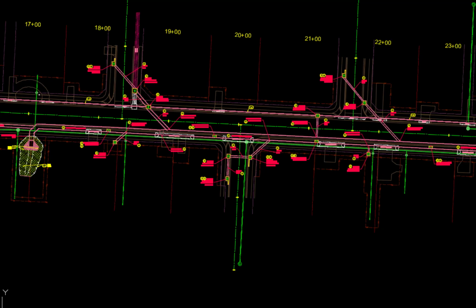In areas where the subsoils consist of clayey materials that do not drain well and become saturated during the rainy season, which is the case within the Kincaid road improvements, subsurface drainage should be installed along roadways in order to keep the subgrade dry. Where stormwater drainage facilities are installed, gravel is used for the bedding and backfill of the drainage pipe, which also serves as subsurface drainage.